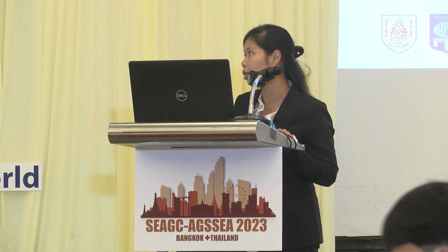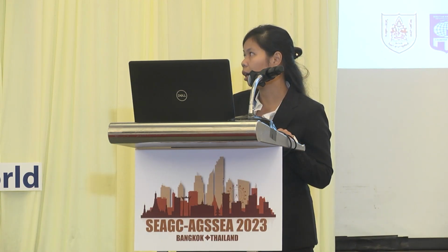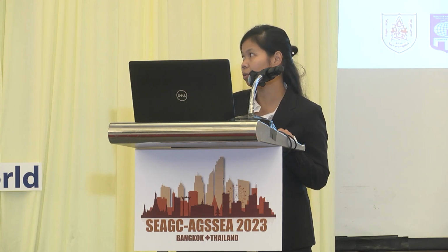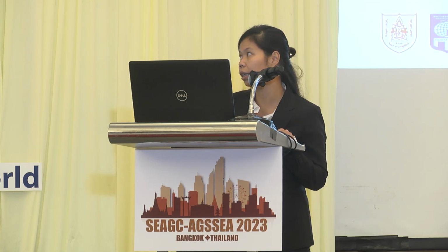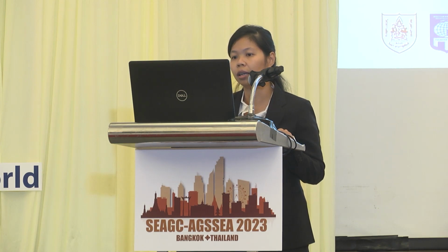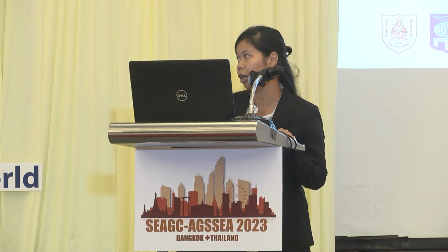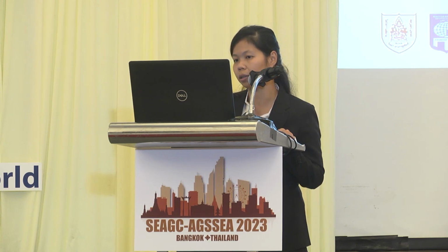Okay, so this is the project detail on the proposed HDD work. For this project, we are using 8 numbers of 110 mm HDPE pipe. The drilling length is about 85 meters, and the maximum reaming size is about 500 mm. The depth ranges about 5 to 5.5 meters. And the number of pits is 2, which are entry and exit.